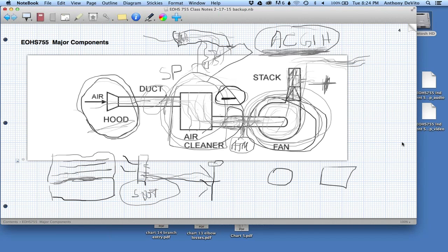You see arches in architecture going back thousands of years because ancient architects understood that the circular shape is particularly strong. So when you have a lot of suction, a very large negative pressure, you could actually collapse the ductwork, and it's a lot easier to collapse square or rectangular ductwork than round ductwork. If you've seen square ductwork come under negative pressure, you may have noticed that it buckles in as soon as the fan goes on; you hear a clunk and see it buckle in a bit. So the real reason we want circular duct on the suction side is because it's much stronger and more rigid than rectangular duct. On the discharge side, it's less of an issue. So we want to keep that in mind.